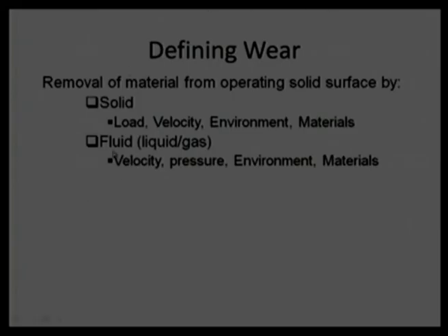When we treat wear by a fluid, we say that it depends on the relative velocity and on the applied or induced pressure. Here we do not use the word load, we use pressure, because we know there will be a uniform distribution, while in the case of load there can also be a concentrated load. So, that is why we use the word pressure here. Of course, the remaining two parameters will be the same, environment and material.